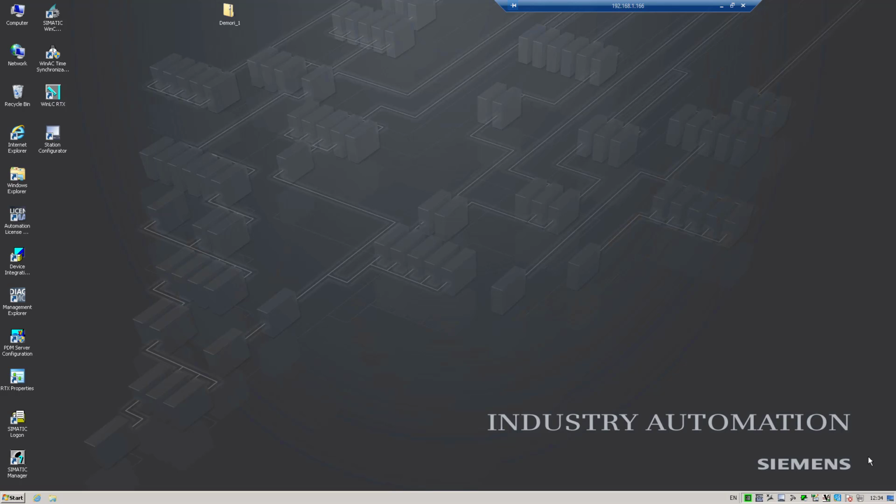During the initial setup of the device, it's important that you set the PC name and a login password. That is going to be required later on for PDM Server. And try and follow the PCS 7 convention, so no special characters in the PC name.